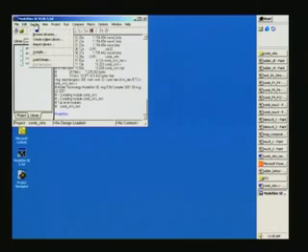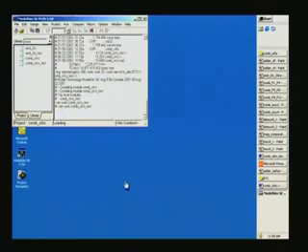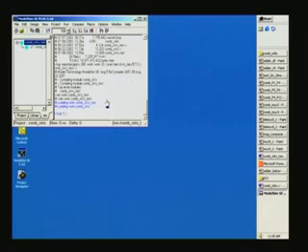The next step is to load the design, and what you have compiled will have to be loaded. It opens another window, the load design window we have seen. Once again the module of interest is combinational_circuits_test, that is the test bench. Double click here, or you can single click and then say add and then load. Let us see if there are any errors.